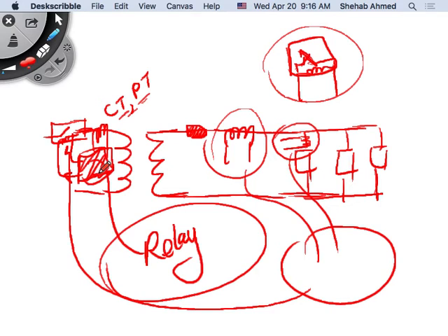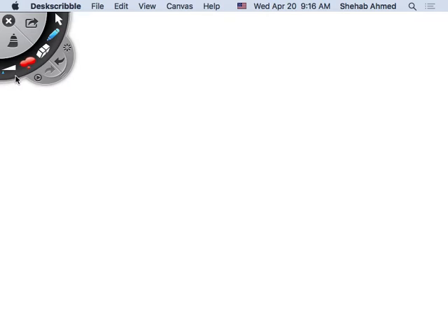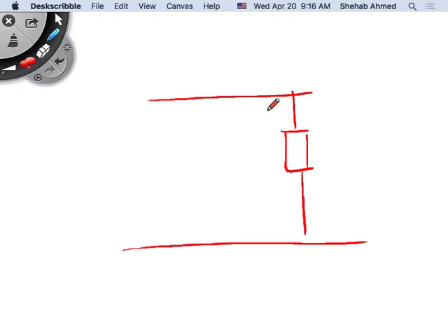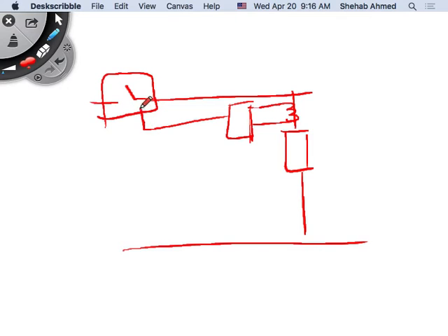Right? So these are the three components of a protection system. Chapter 10 is about, okay, where do you put these CTs and PTs? Do you put the CT here? How about if I want to protect this load? One idea is I can put a current transformer here, and then this current transformer is connected to a relay. This relay is then connected to a breaker that is here, and it tells this breaker to turn on or turn off. Right? That's one way.